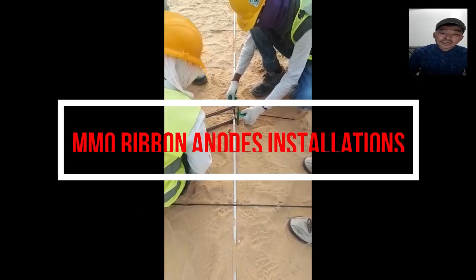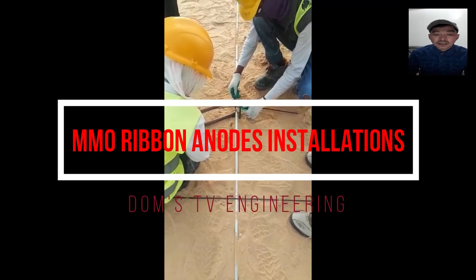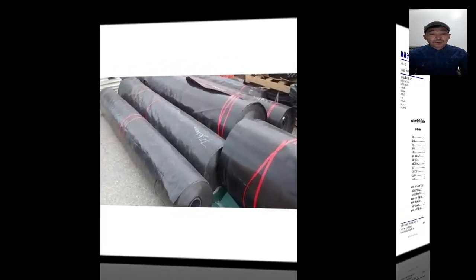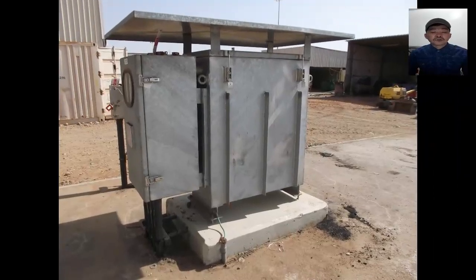Spot welding is required at each crossing of each MMO ribbon anode to titanium conductor bar and titanium to titanium bar. The sweet sand and cement mixture under the tank bottom inside the foundation shall be according to 32-SAES-005. A 1000 microns polyethylene liner shall be provided under the tank bottom. The recommended distance of the power transformer rectifier shall be 5 meters from the tank, otherwise properly designed cable length shall be considered.